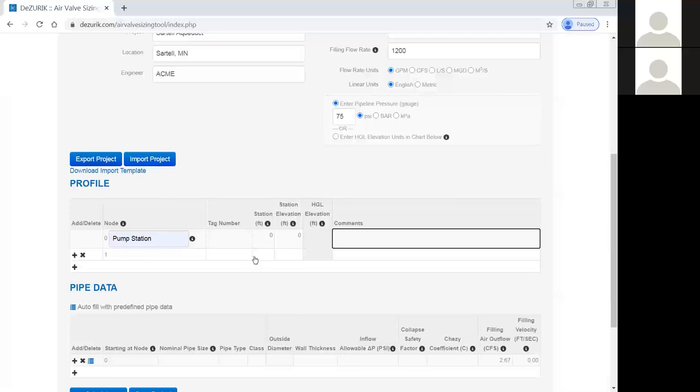I can add the next piece of data in by clicking here, which is what I'll do, and then I'll explain in a little more detail something that's easier. But we're going to make our station 750 feet, and our elevation is 20 feet. By now, some of you might recognize it's the same example that's on the slide rule. And I happen to know that that's a high point, and this is an optional piece of information, but it's useful to me. So why not put it in there, high point?